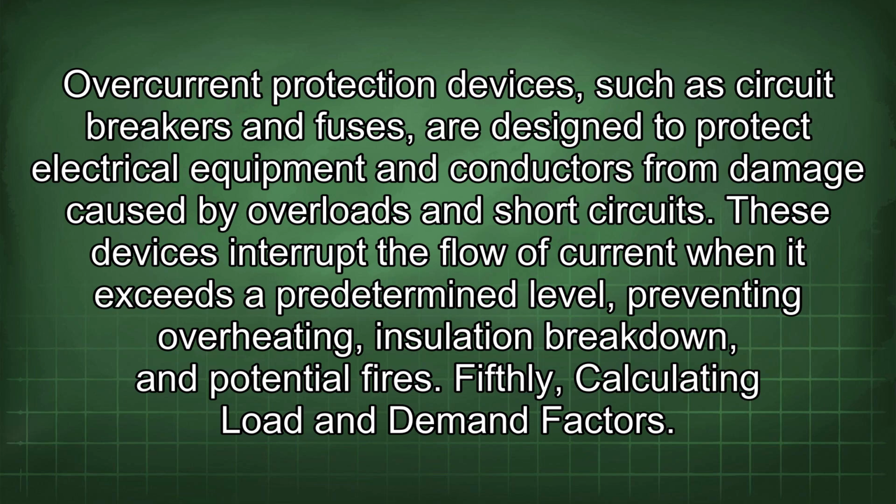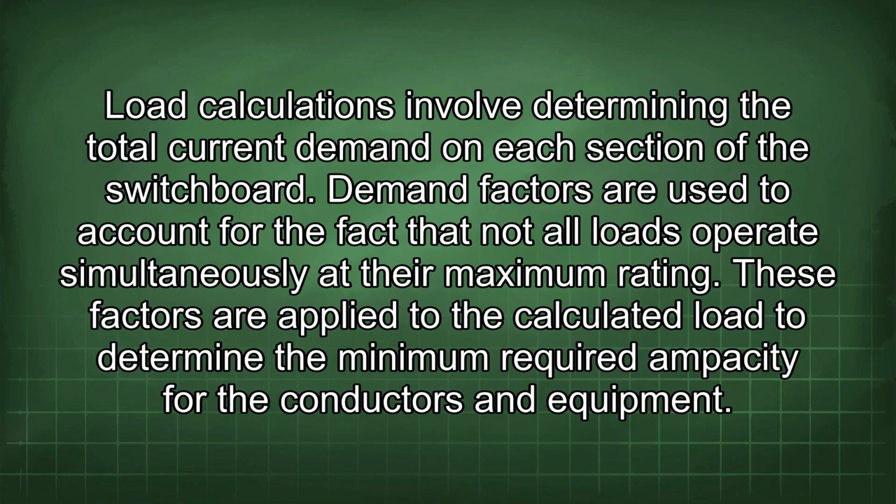Fifthly, calculating load and demand factors. Load calculations involve determining the total current demand on each section of the switchboard. Demand factors are used to account for the fact that not all loads operate simultaneously at their maximum rating. These factors are applied to a calculated load to determine the minimum required ampacity for the conductors and equipment.